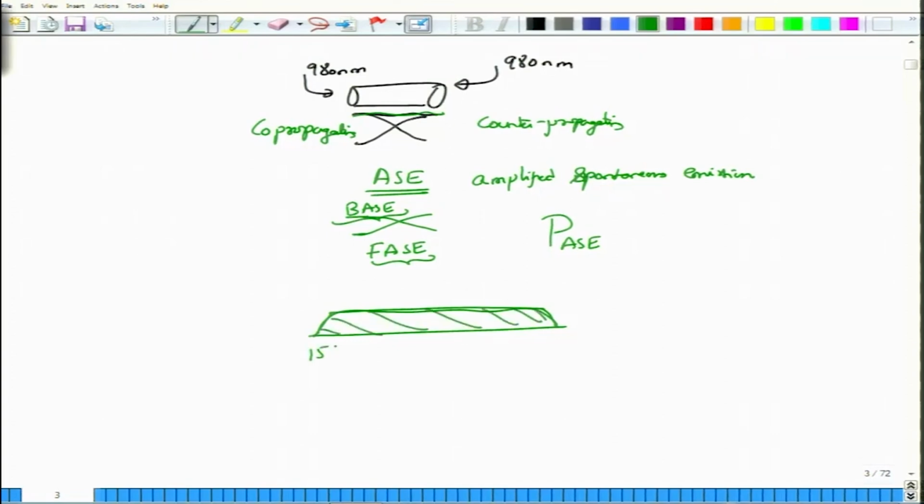It can cover all the way from 1500 to about 1560 nanometers, which is the range we are normally interested in. Of course, you do not use the entire range for a given channel. Each channel will have a certain band, as we talked about in the previous module. Over that band, if the bandwidth is say B0, the total noise power present in this band is given by